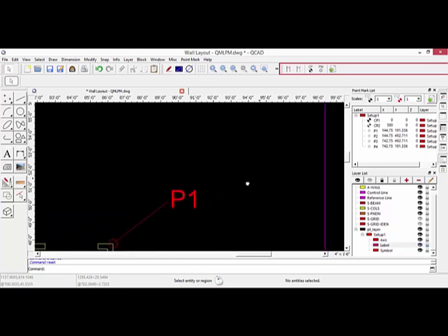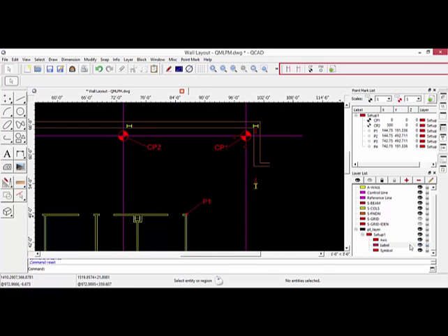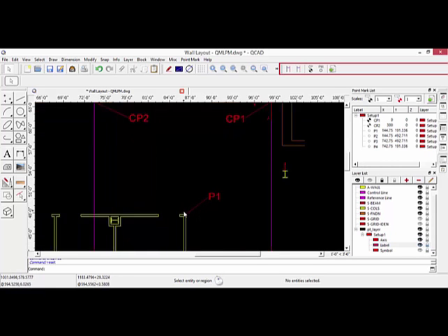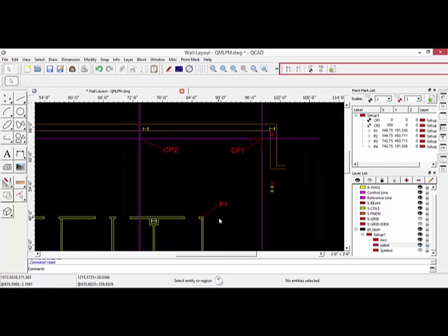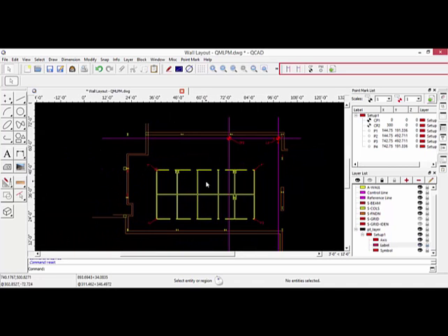So let me zoom out a little bit here. If I click on axis here, you notice the XY label that's on the first control point is turned off, so you can actually see where the XY axis is. And then the next thing is the symbol. If you click on that, the actual symbols themselves, the circle or wherever the point is, are turned off. So you have layers that also control what you're actually drawing inside of QCAD.